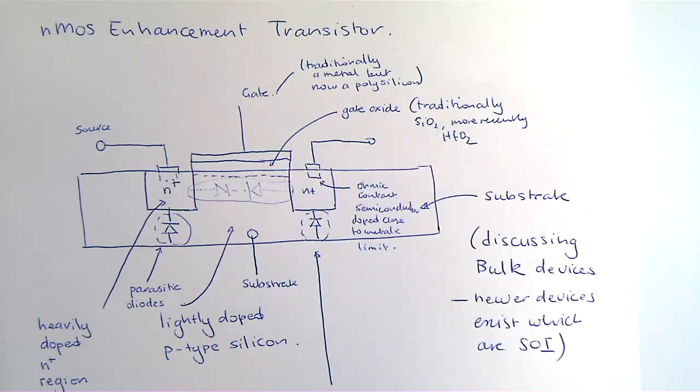That was one of the large advances, because hafnium oxide has a high dielectric constant, can be thin, and it has low leakage, right? Because as you make this thinner, you get tunneling of electrons, and that causes you to consume more power, right? So therefore what you want is a dielectric which has very low leakage, and hafnium oxide is one such dielectric.